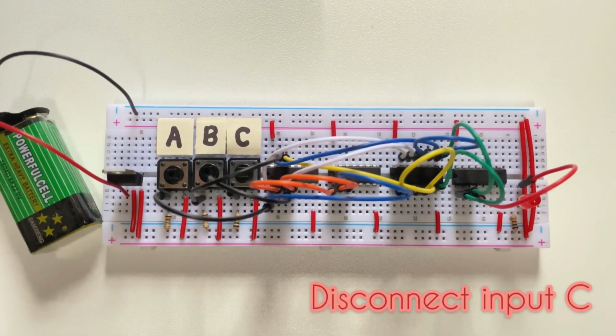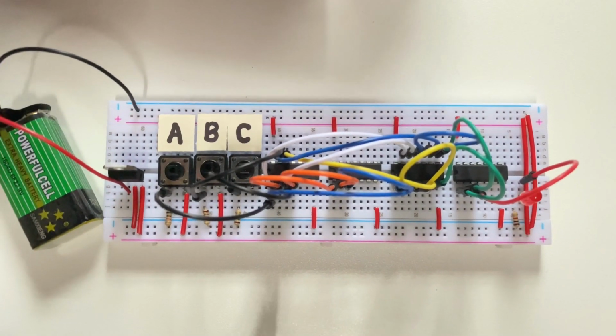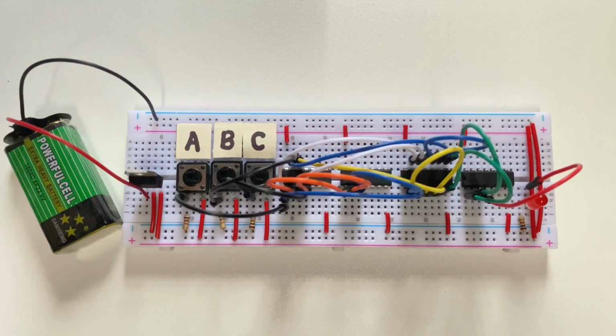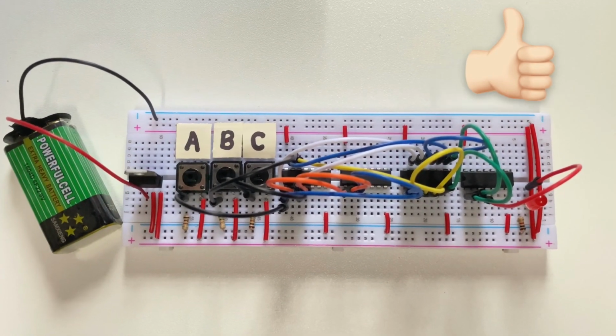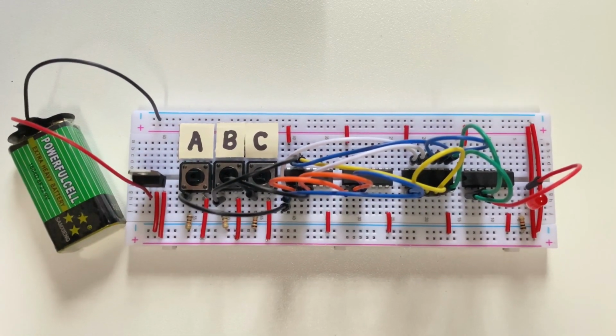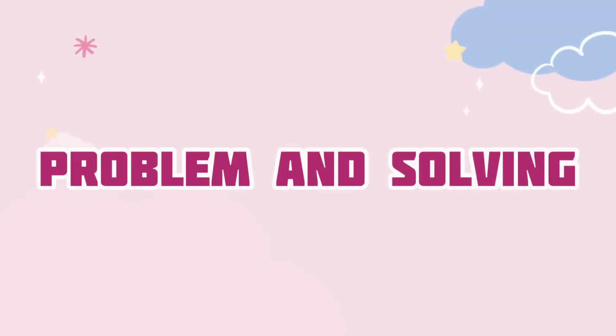And if we disconnect the input C, the output is 0. So this proves that if one of the inputs is disconnected, the output won't behave like the truth table. So the output is in a floating state.